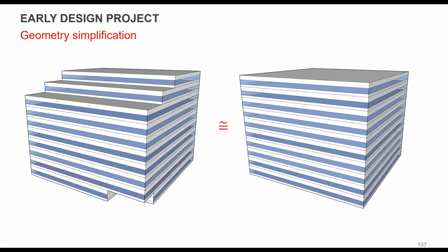Other simplifications have an effective geometry that's the same for every floor instead of doing the variation. Anytime you introduce this sort of difference on floors, then you add complexity, because a lot of the tools make it easier to put a multiplier on a single floor, so you're not having to enter that. So in this case, the one on the right, I would have a ground floor which may or may not have exposure to a garage or to the ground, and then a top floor which has a roof. All the intermediate floors could be done as separate elements there.